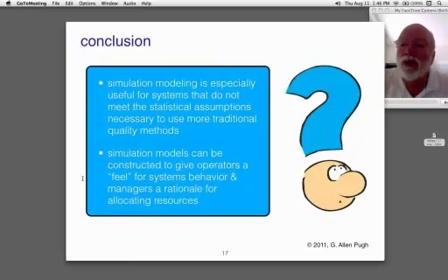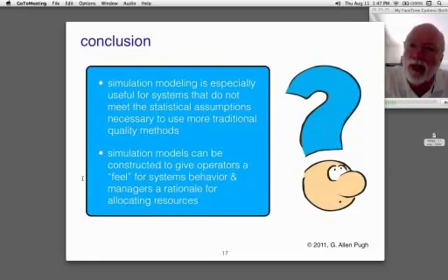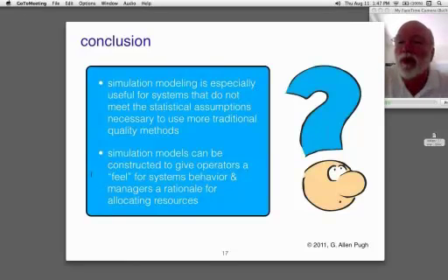Are there blocks specifically made for quality system simulation in ExtendSim? Only the ones I showed you. In fact, I've never had to write more than 2 or 3 blocks to do quality system simulation in ExtendSim. ExtendSim includes enough blocks that it's fairly easy to use the standard blocks, which is actually a good thing because writing your own discrete event blocks can be challenging, although writing your own continuous blocks is actually fairly straightforward, just simply an equation block. Dave, feel free to jump in here if I'm insulting you in any way with my knowledge or sort of lack of knowledge.